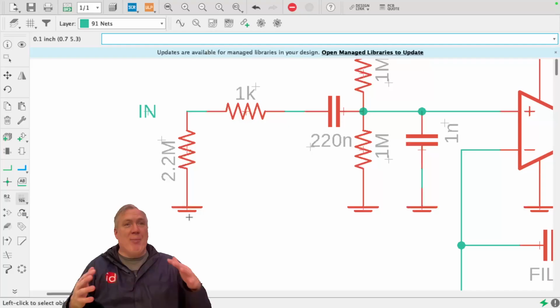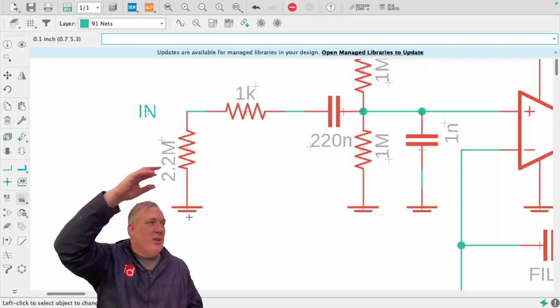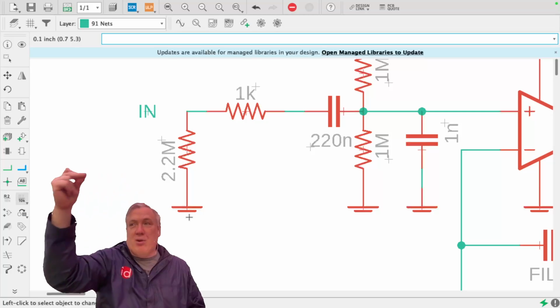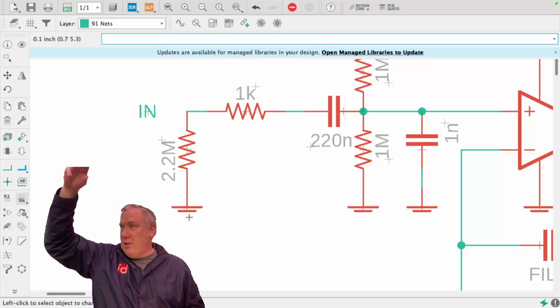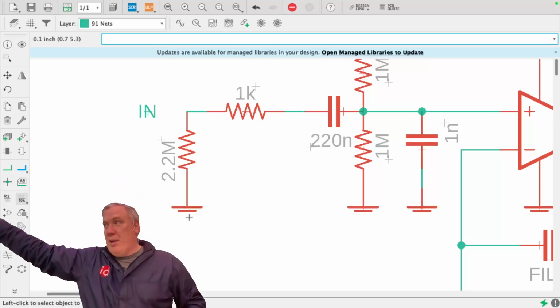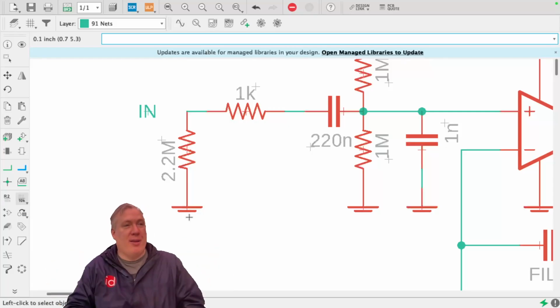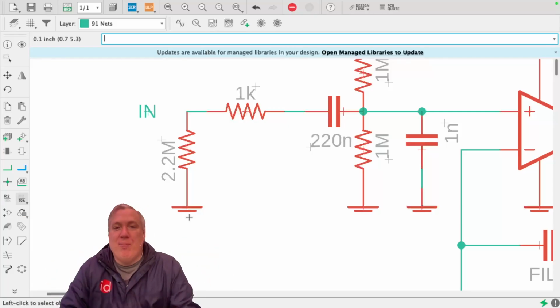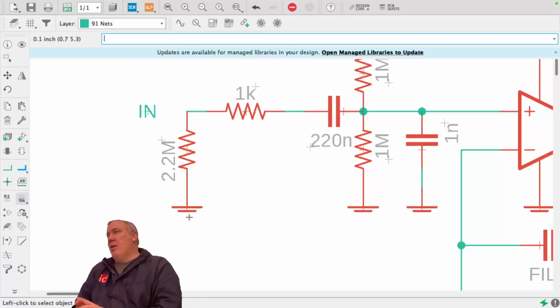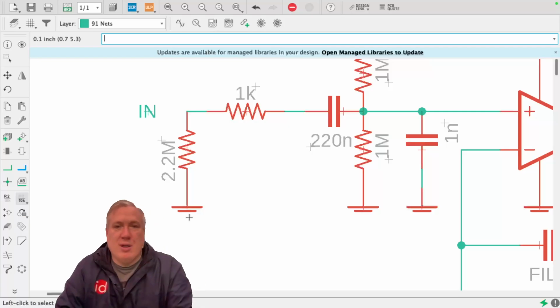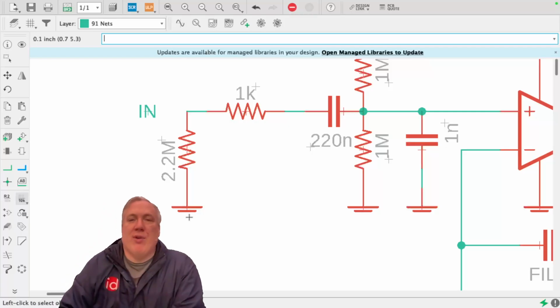And if that happens, that means that there's a little bit of voltage on your input. If you immediately turn on the pedal with some little voltage on the input, that voltage will get to the output and you'll hear a pop when you turn it on. So by dropping it down to 0, that will help it stay at 0 when your pedal's off and there's nothing connected. And so that's for the input.